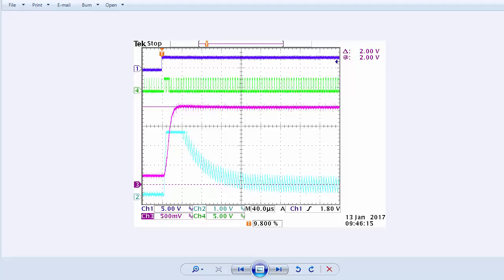These kinds of hybrid systems, where we mix open loop and closed loop operation, are generally a practical way to achieve desired performance under specific conditions, assuming the load is known and the set point step is known and the system is not changing. This can be especially useful if we want to squeeze every bit of performance from our system.